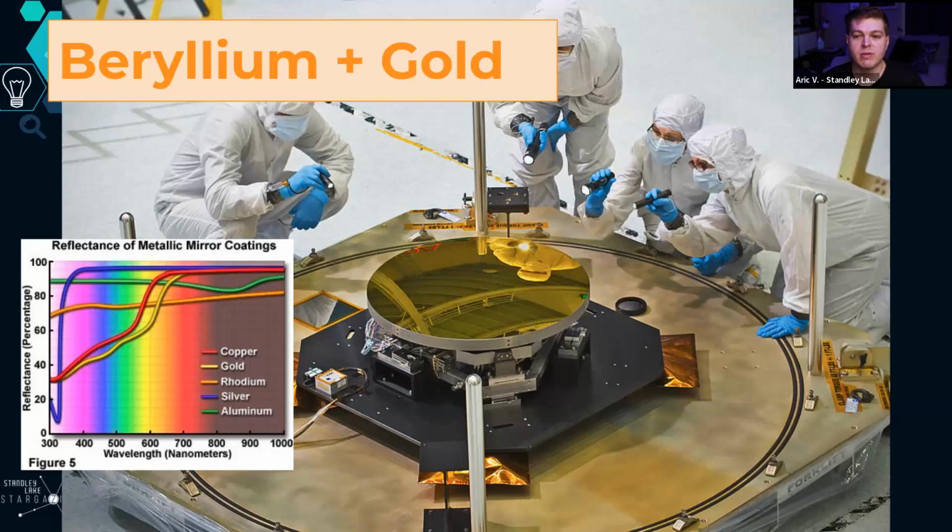Well, copper and silver are okay. In fact, they're very good in the reflectance criteria, so they meet that. The problem is that they both oxidize very quickly. So they basically degrade and erode, and then the clarity of the surface drops, and then you don't get useful information. So the light coming in gets scattered in all directions, or you have bare patches where it's just beryllium after a while. So that is not helpful.